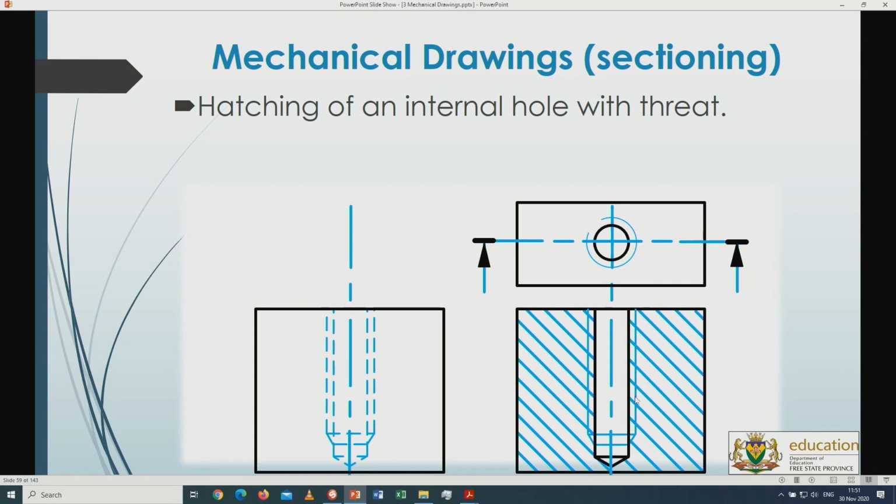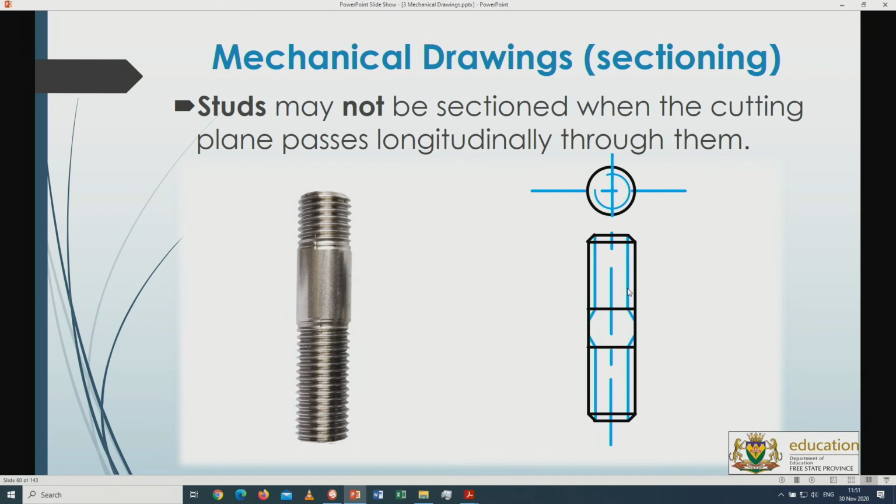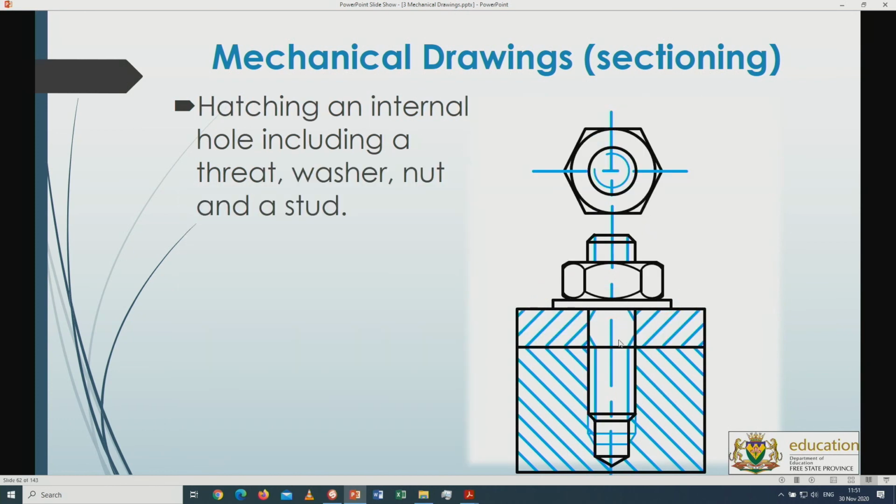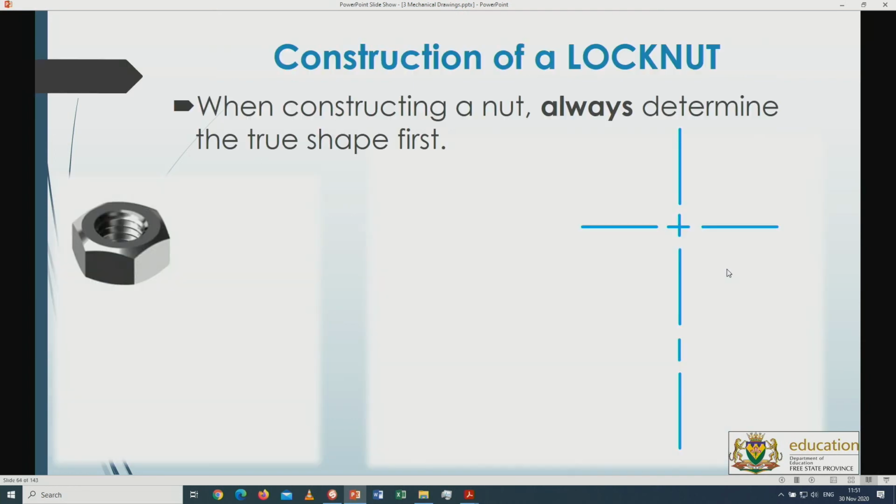There's some material in there where the thread is. Now if I of course put the stud like this one, place the stud inside the hole, diameter will be from side to side. The threaded part will be 0.8 smaller, so we can add this part. First the washer, place the washer in, and then we can add this area of the stud, and then turn the bolt in on this part. I will get to that just now.